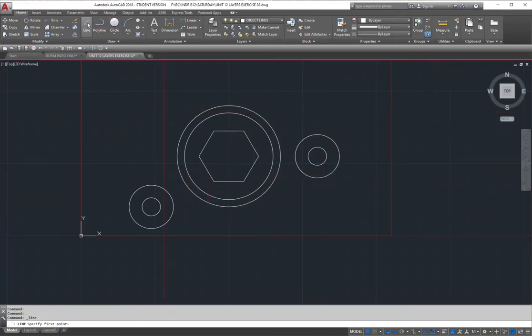If I go and just snap to whatever I find right here, that's my object snap. Remember, my object snap. So if I go from here, it's going to go from quadrant to quadrant. See that? It cuts through this part and it will go straight through the circle, so it doesn't give me a nice smooth transition, so that doesn't work. So it has to be a tangent point. So remember, the fastest way will probably be if I just go and I say, well, line, right?